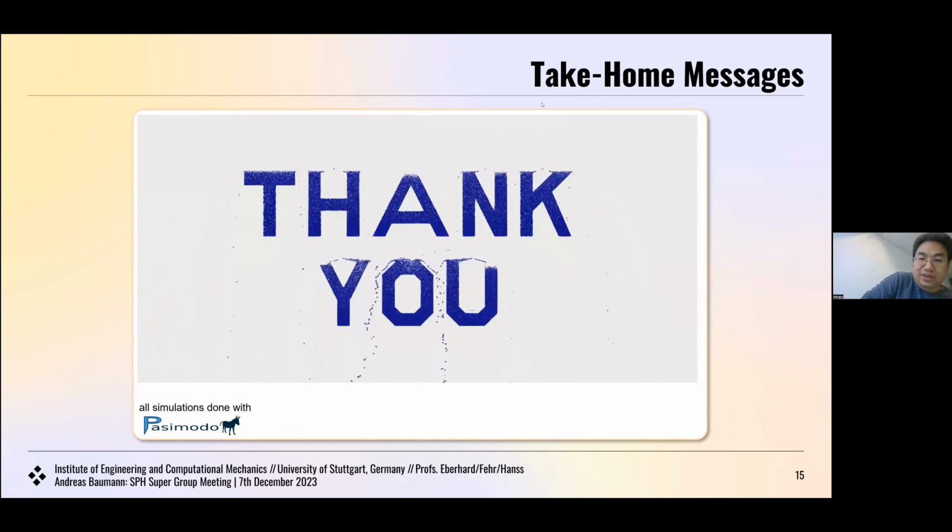Exactly. We do two different approaches. Our in-house code originates from a DEM solver, so we have a monolithic code which is then extended by SPH. So we have a monolithic coupling of the DEM with the SPH. We do this by applying, as already mentioned, a repulsive force function, which gives us the forces between the particles. The second approach, which I applied for the finite element model, was a segregated approach.